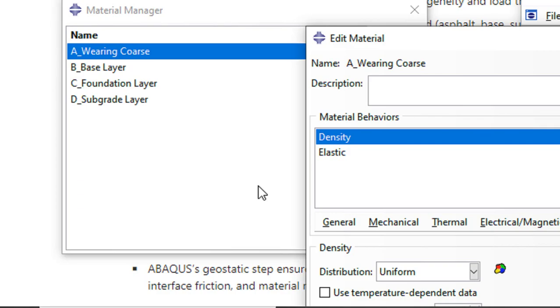Soil modulus represents stiffness and is modeled using ABAQUS built-in material models, that is elasticity here. And if you are working on more critical state models like the modified Cam-clay plasticity model, you can capture the elastoplastic response as well, right?